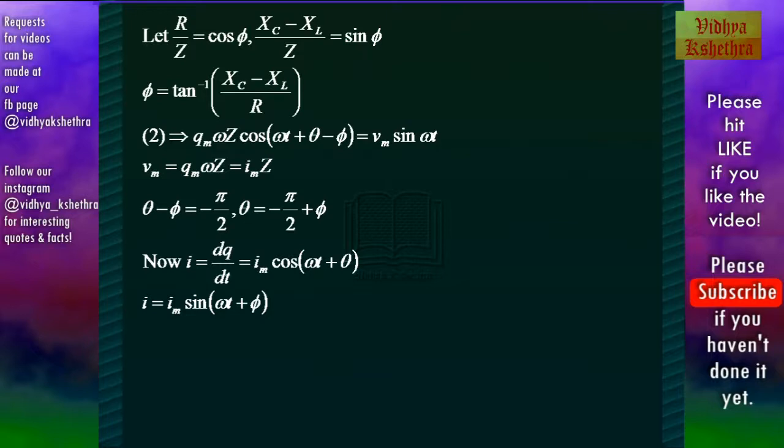Now we have to compare both these sides. So Vm is equivalent to qm omega Z, and we can write qm omega is equal to Im, and theta minus phi is equal to minus pi by 2. So theta is equal to minus pi by 2 plus phi. Now we know that i is equal to dq/dt. Substituting these, we get i is equal to Im cos(omega t plus theta). Now for theta, it is minus pi by 2 plus phi. Therefore, i is equal to Im sin(omega t plus phi).